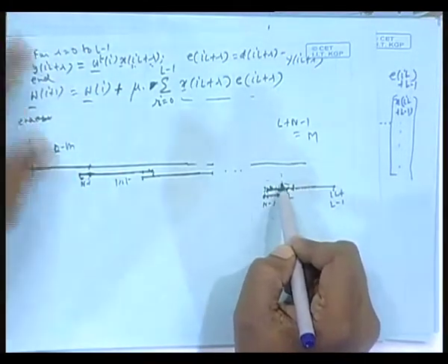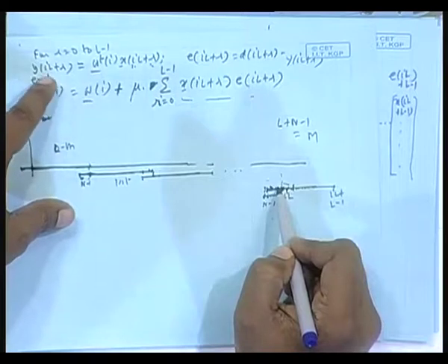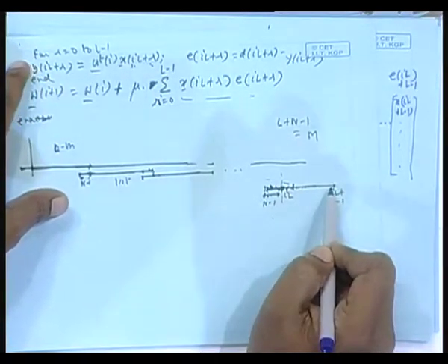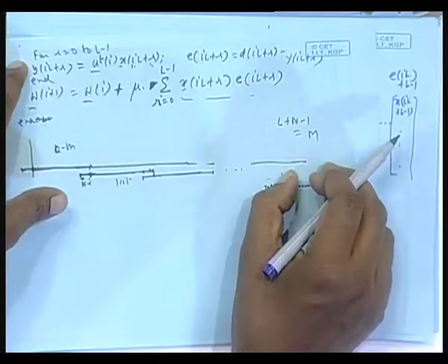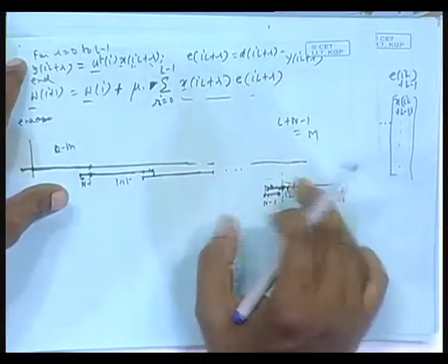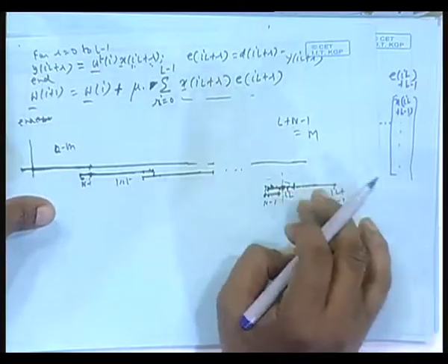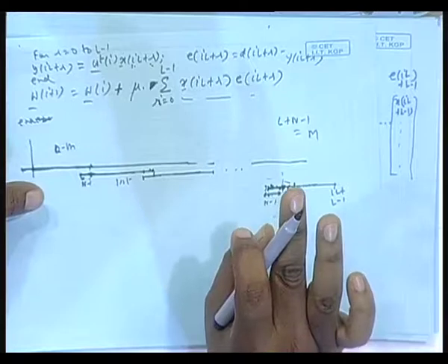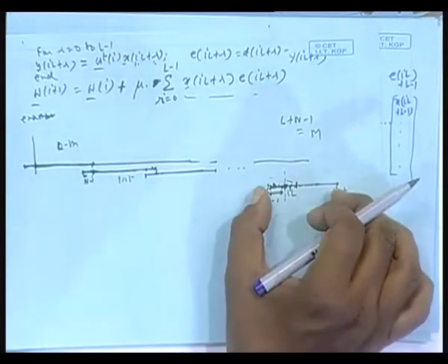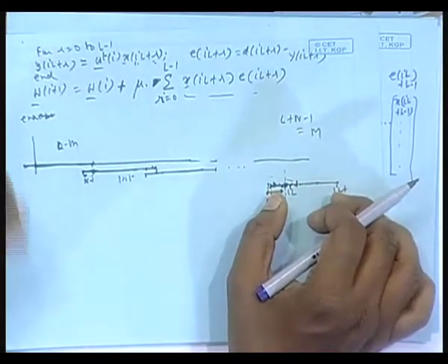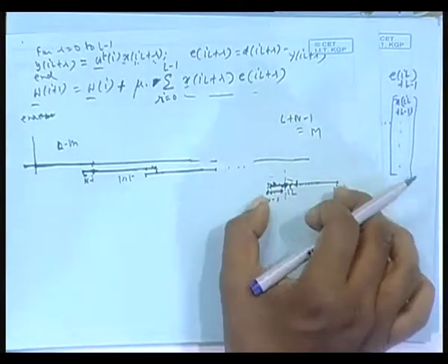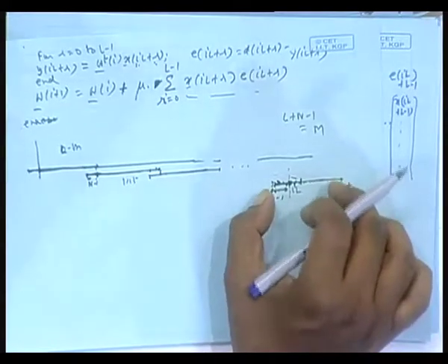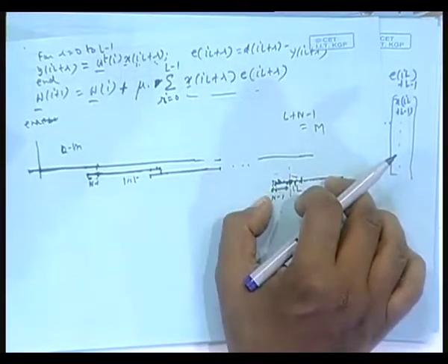Filter length was less, capital N here, and this total length is what? Capital M. So, you have to have extra zeros. Then if you do circular convolution and throw away the first n minus 1 samples, you get the correct output, isn't it? So, that time I need circular convolution means what? I will be doing in frequency domain DFT and then finally inverse DFT, DFT into DFT, then inverse DFT of that. So, I have already computed the DFT, this DFT once.